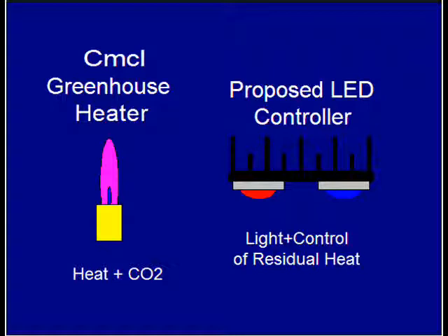If I'm running PWM, that's a lot less efficient as far as optical output, and same with driving the LEDs really hard. Their efficiency drops down. So I'm thinking I can play some games with that, and I can generate more heat or less heat and vary the spectral content around a little bit by having multiple channels on the PWM output.